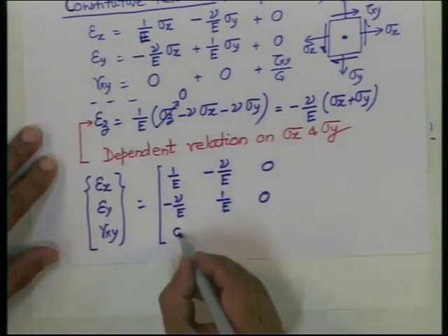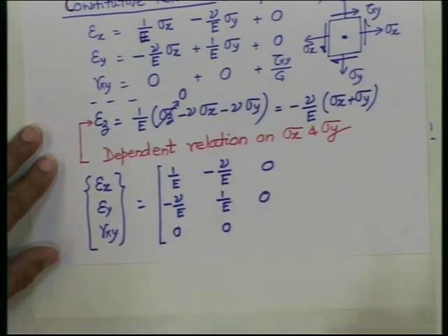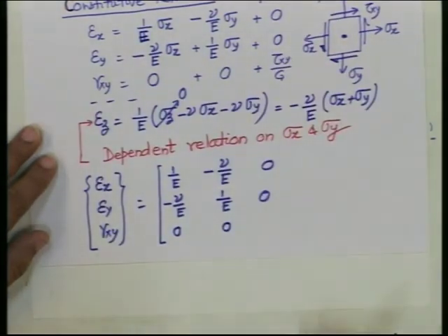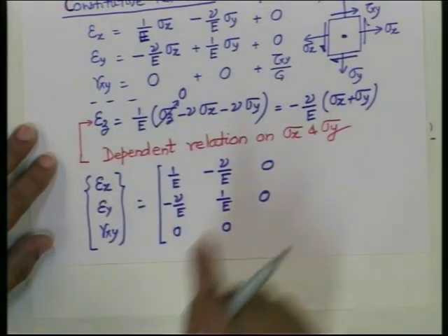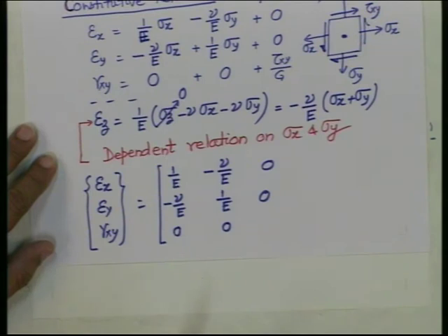No, you think about it. Why should it mention? Honestly, at any point, if you find out from your plane stress analysis sigma x, sigma y, epsilon x, epsilon y at each and every point, knowing those quantities, you can get this at each and every point. You don't have to do it. So, there are two types of quantities in any field. One is called dependent, other independent. So, it is not independent. Okay. So, it will not appear in your computations. Computation means it is a trivial computation.